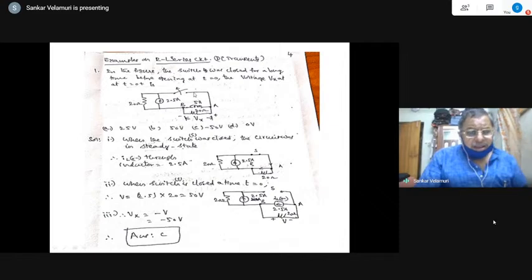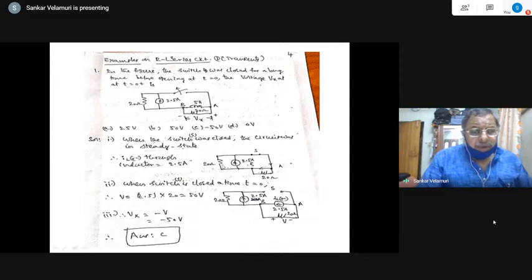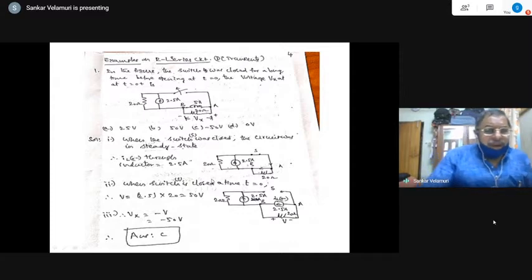Okay, so it doesn't matter whatever way that is being given. Otherwise also you can take this as 2.5 A and 20 ohms, or 50 volts in series with the 20 ohms, using the equivalent source transformation technique. So 50 by 20 is 2.5 flowing from this, so flowing through AB, right? So that is how you have to think. Either way it is the same.